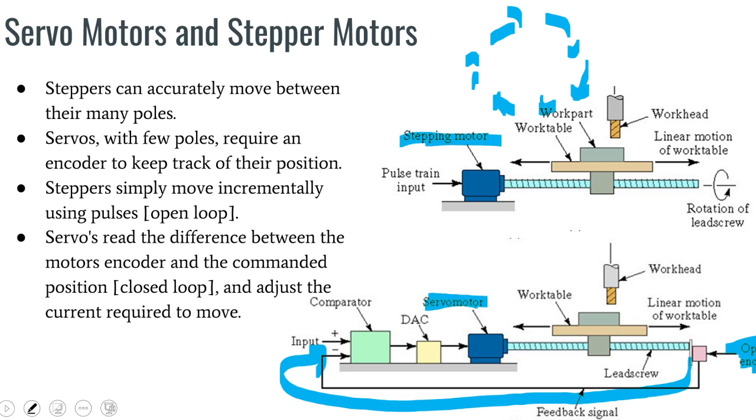Whereas in the stepper motor, we can directly give the input to make smaller, accurate movements. In the context of open loop and closed loop systems, stepper motors would normally function in an open loop fashion, making a move with every increment of pulses, whereas servo motors function in a closed loop fashion, and they adjust their position based on the feedback gained from the output.